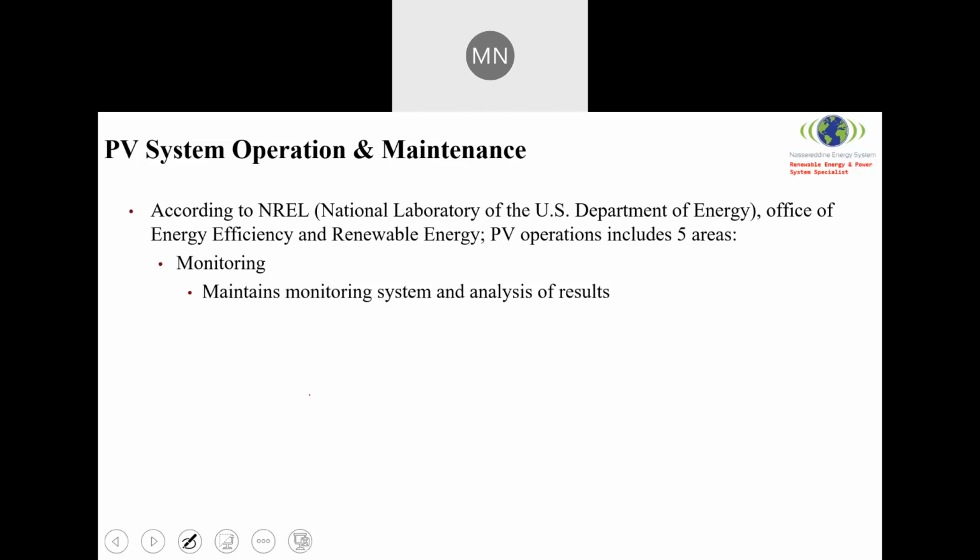So as part of your system under operation, you should always make sure that you maintain a monitoring system and analysis of the results. You need to analyze the results. If you see a sharp increase or a sharp decrease of some sort of load, you need to check the situation. See, will this impact my inverter, my energy storage capability, or would it cause any damage?